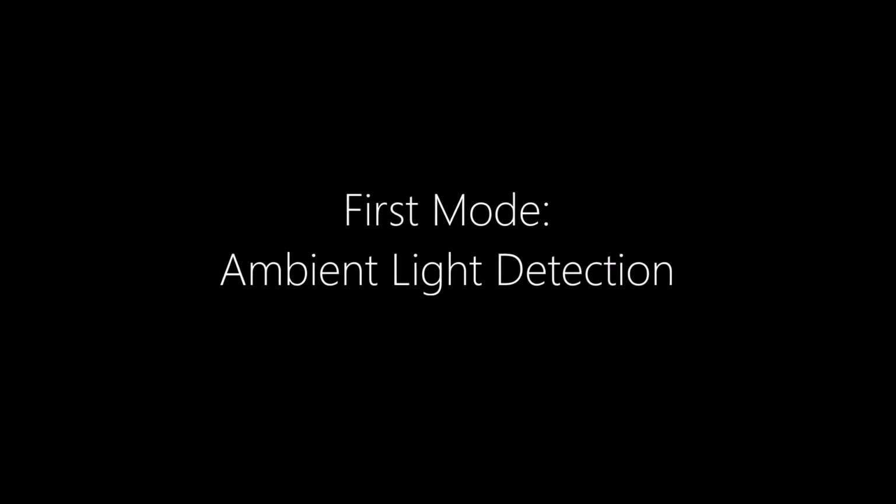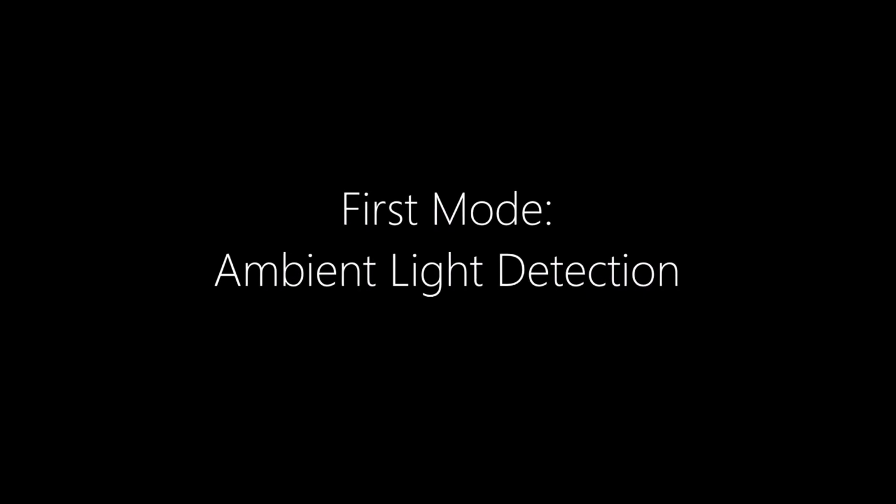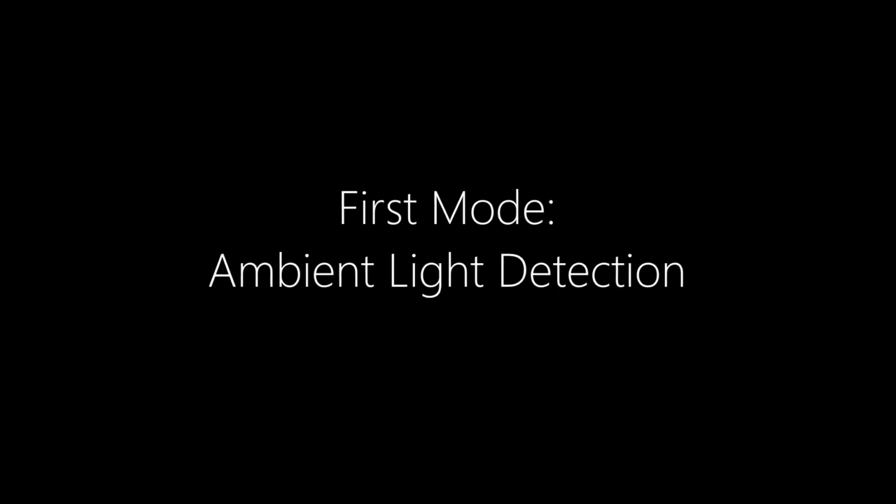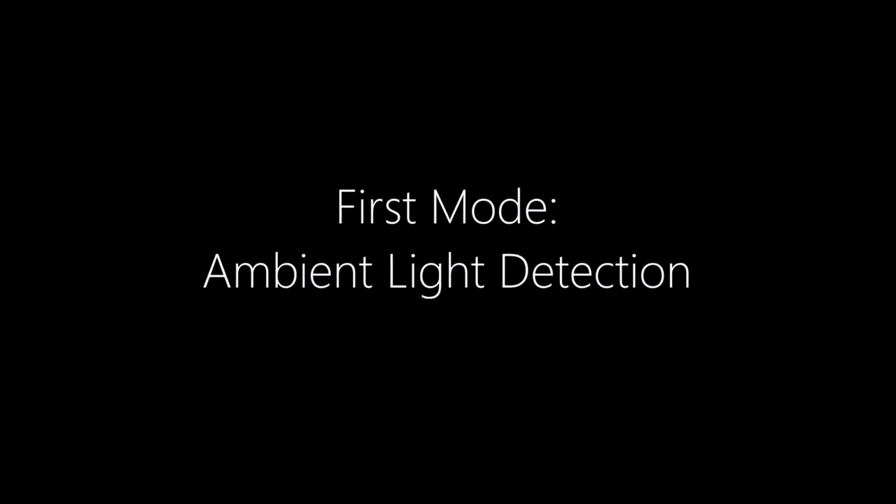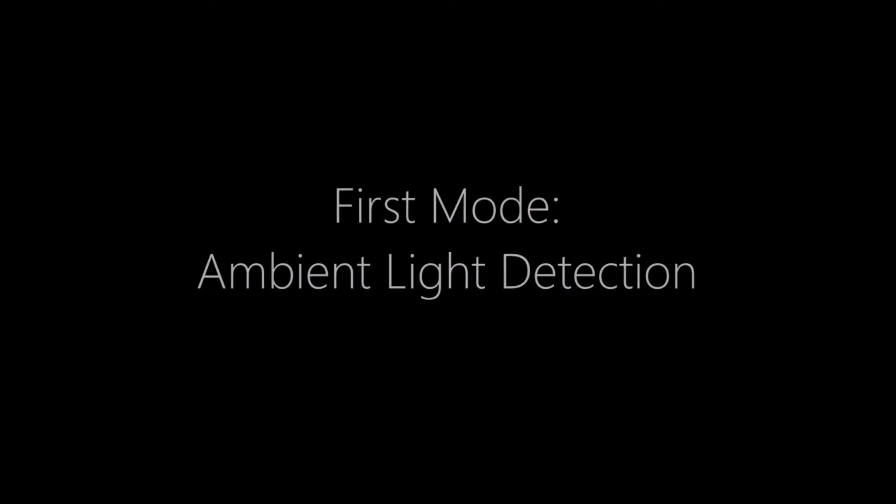Ambient light detection. The system switches the headlamps on and off depending on the ambient light. The ambient light is sensed by the photoresistor, which changes resistance according to the amount of light falling, which is recorded by the code. It is assumed that for a certain amount of light the headlamps would be off, and any light amount below that would turn the headlights on to full brightness, enabling good visibility.